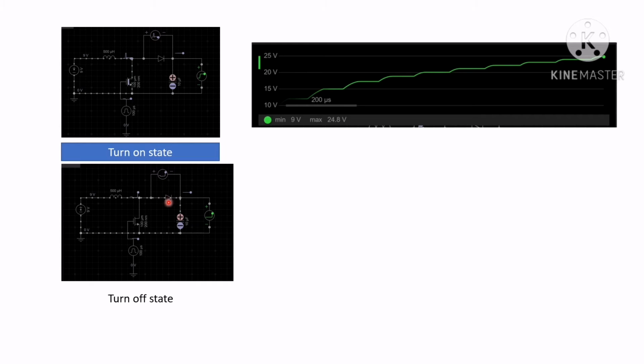Because there is a diode over here, this stops current from flowing backward, which means it only allows current to flow back into the DC voltage supply again over here. From the capacitor to the switch, once it turns on, and back to the power supply.